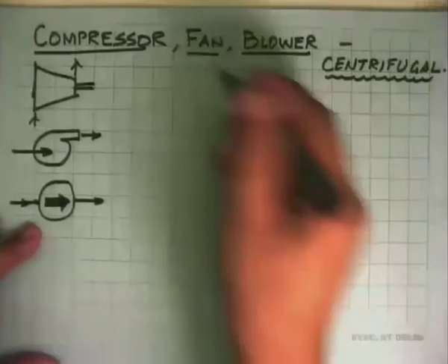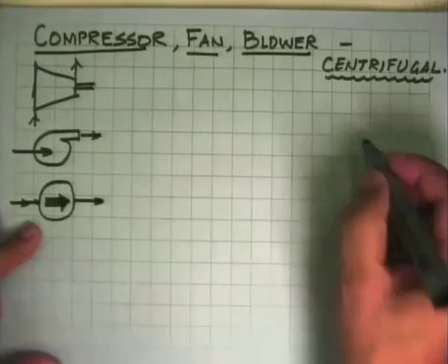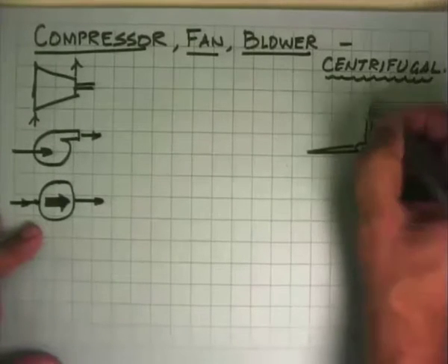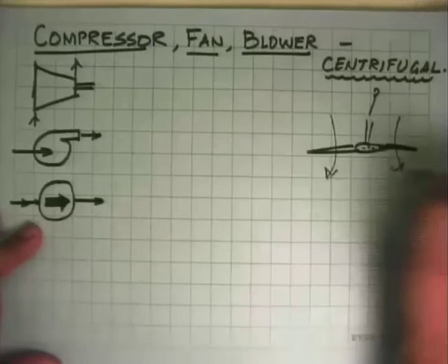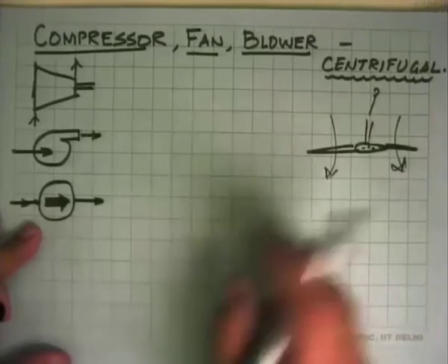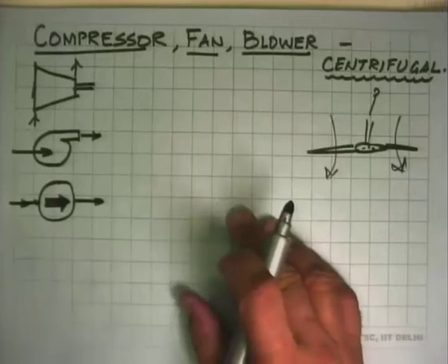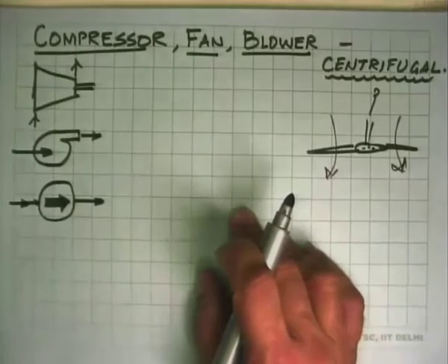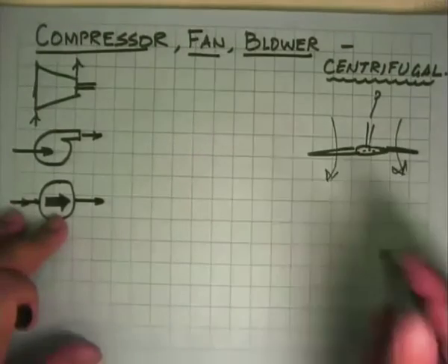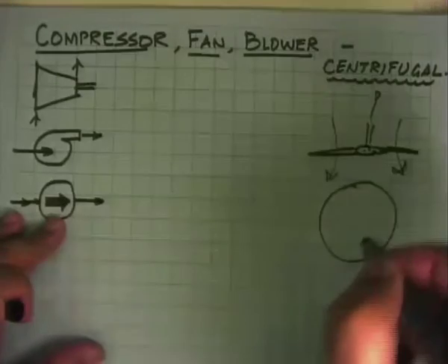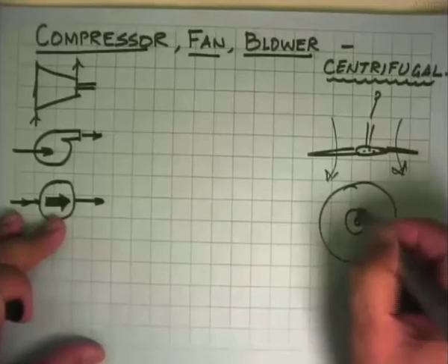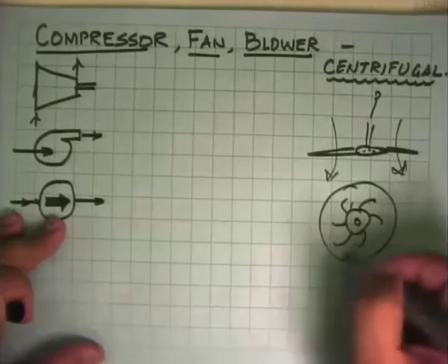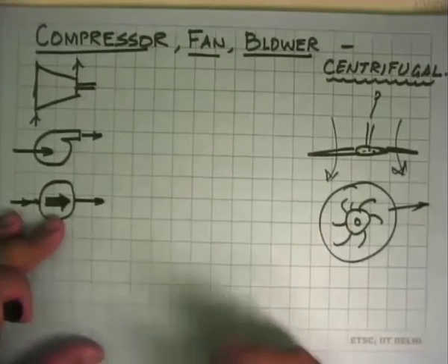So the simplest example of a fan is your ceiling fan. So all you have is a hub with blades on it, and there's a motor inside this, so you give electricity to it, and it causes an airflow over there. So the same thing with more blades, like this exhaust fan of the kitchen or the bathroom, that would be a fan. A blower is slightly different. You would have seen a blower in some of the desert coolers, where there's a circular device into which air goes in, and on this there's a wheel with these type of things. This is rotated, and as the air comes in from this side, it throws it out on one side. That's one type of a blower.